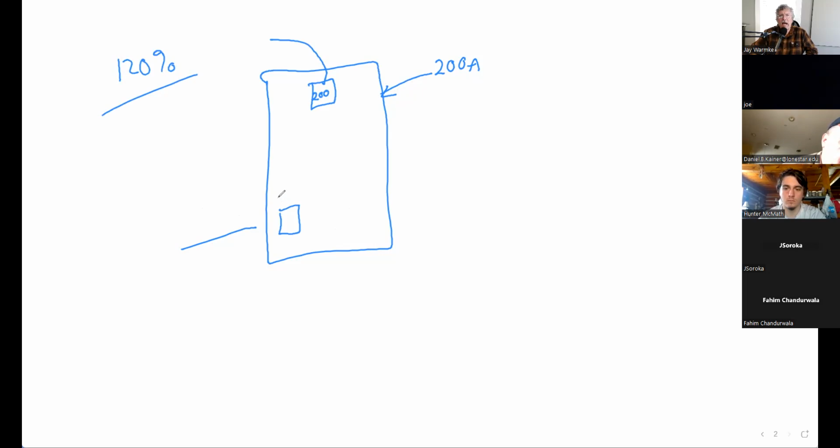So that means I can come in here with a 40 amp breaker, right? The logic there is that you almost never run all of the power. How many people have popped their main because they ran too many electronic devices in their home? It happens very, very rarely. So I could come in with a 40 amp circuit for my array in a 200 amp panel.